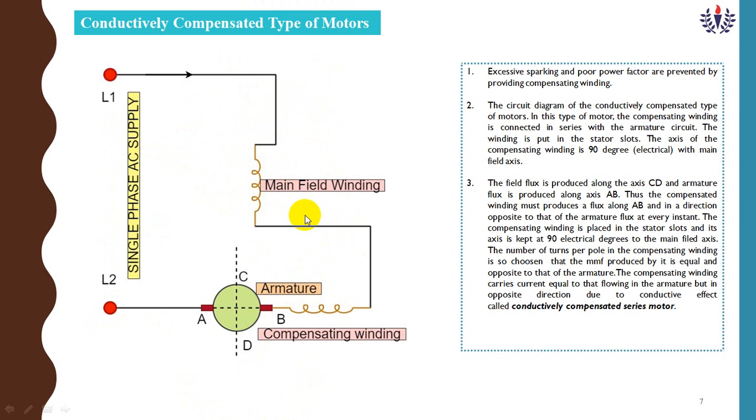Now I am going to add a field compensating winding. This compensating winding I have to connect in series with the main field winding and armature. Students, please look into this diagram.